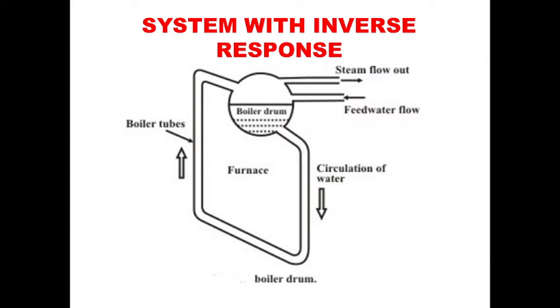It is essentially a system whose transfer function has a zero on the right half of the plane. This type of system is called a non-minimum phase system. An example of a system with inverse response is the boiler drum. This figure shows the boiler drum.